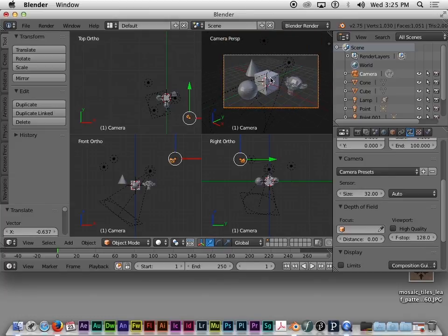How did you get, because mine still says user perspective? Yeah, so to change it, make sure your mouse is located out in your viewing windows. Then you can hit 0 to convert your user perspective to the camera. Again, Blender is very sensitive about where your mouse is. For view changing, you have to have your mouse out over the viewports. Otherwise, it won't read your shortcuts.